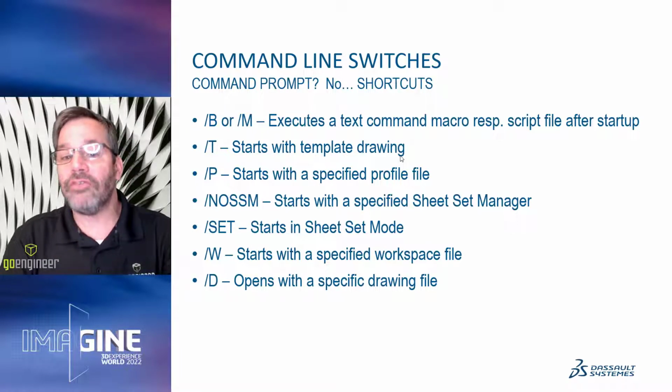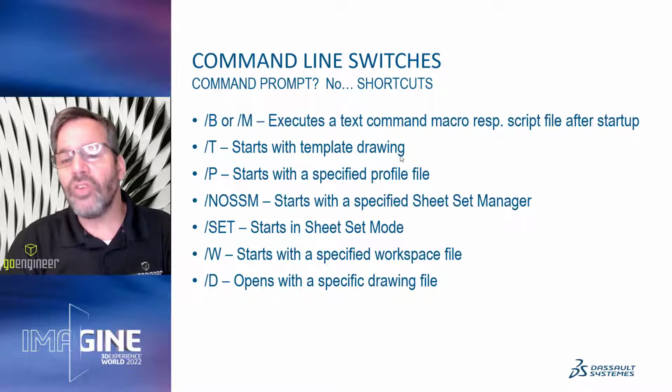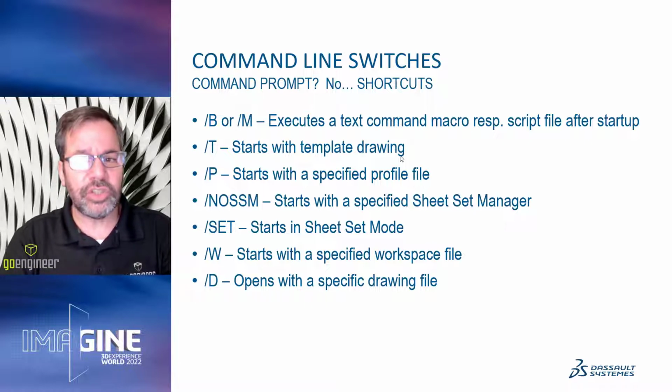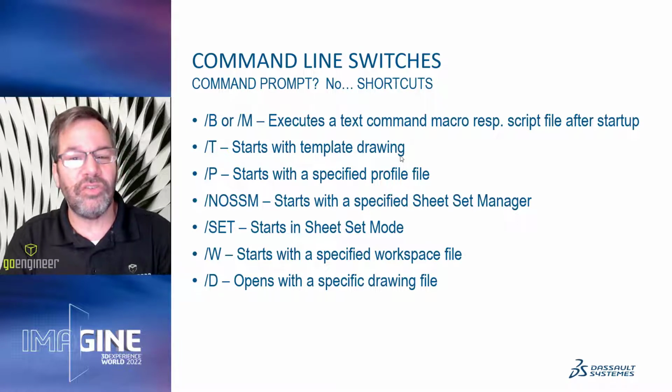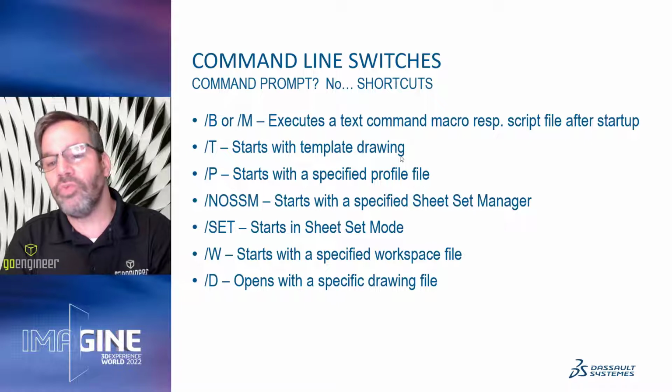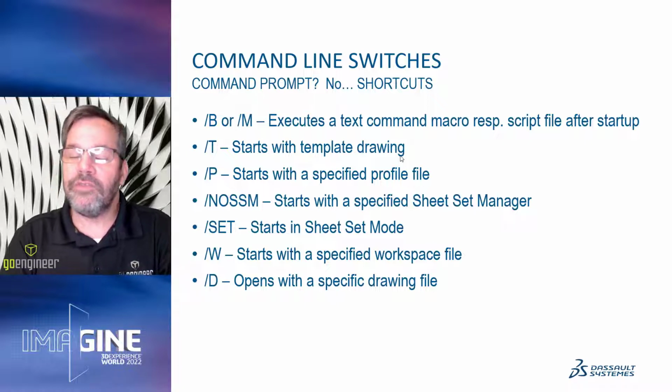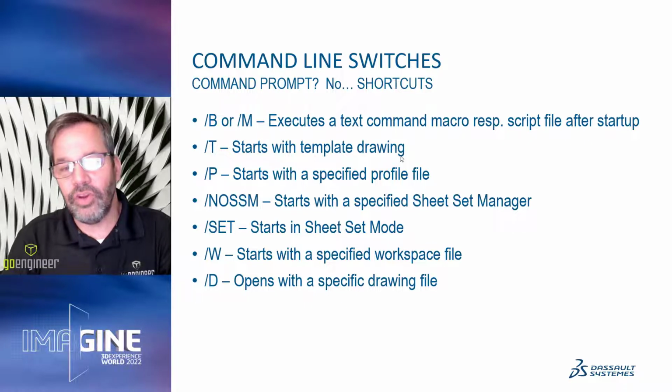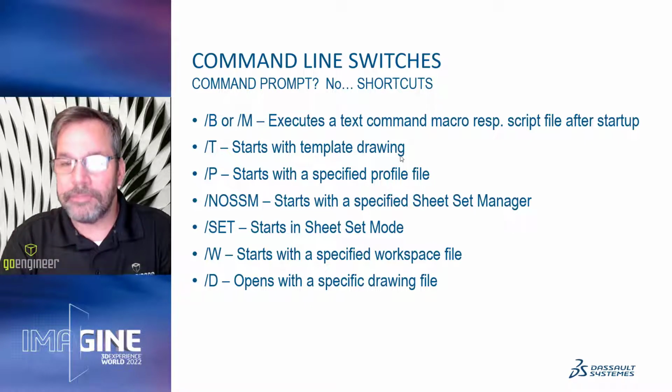Well, now we don't actually work with command line. Nobody types commands anymore into their computer, at least on a Windows-based computer. So how can we take advantage of these command line switches and set our users up for success when they may have different companies that they're going to create drawings for, and we have different setups for those companies? We can do that with command line switches, but instead of using command prompt, we're going to use Windows shortcuts. Now, if you have never created a Windows shortcut before, essentially on the desktop, you can just right-click, go down to New, and say, I want to create a new shortcut.